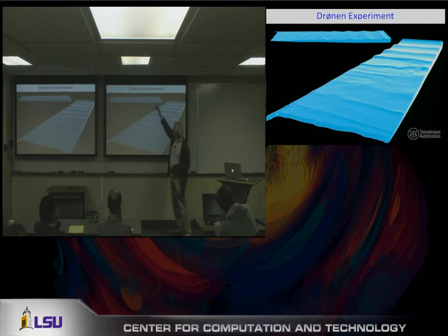So the wave comes across here, and then all of a sudden you see these high frequency things. So there's a nonlinear resonance of shallow water waves that they will separate into harmonics, and it's called harmonic generation. And so it looks like we're getting harmonic generation. So that was a surprise. The water comes in, waves come in here, raise the water level here on mean. That gives a gradient in this direction. The water goes out the rip channel that was there. But look, the wave crests are all bent here.